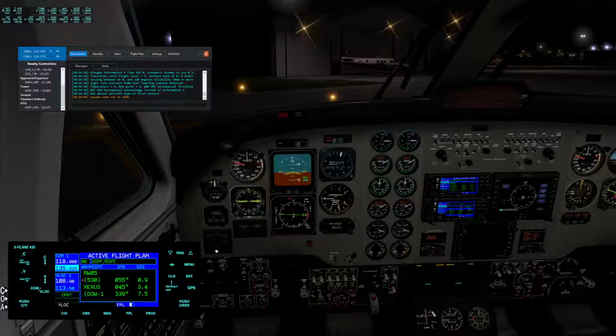By this point, I was thinking, right, I've got to get everything ready for departure, I have to get ready for engine start, I have to make sure I've got the right nav and everything set up. I'd kind of lost the power of speech, so I just stopped any kind of stream commentary. I've just set the heading bug there to runway heading.